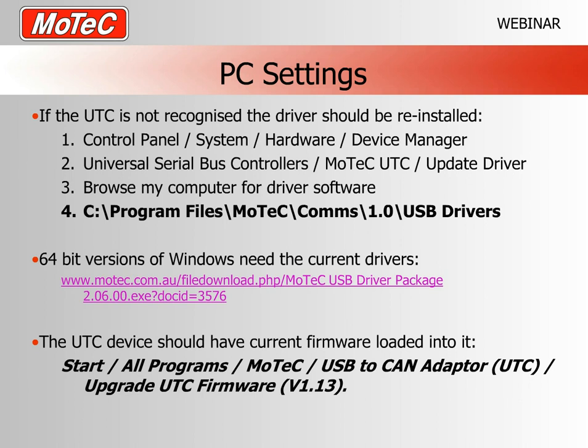Now, the other thing that must be up to date, if you've installed the correct device driver for the UTC device, is that it's also very important that you update the firmware in the UTC. Of course, when these are shipped, they have the current firmware in them, but if your UTC is more than 1 year old, I would seriously suggest that you update the firmware in the UTC, because our later firmware covers a lot more possibilities and is quite significantly different to the earlier firmware.